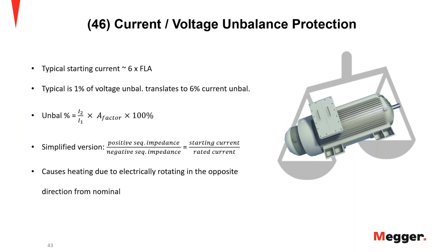Also, a good thing to point out is that you can have unusually high unbalanced values, and this can be caused by incorrect phase CT wiring as well. That can be due to uneven heating, as we saw before in the negative sequence or phase reversal, where we almost went to 1 per unit in negative sequence currents, and that creates a lot of unnecessary heating that we don't need.